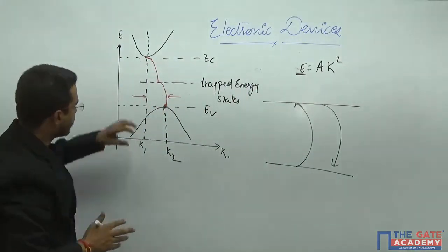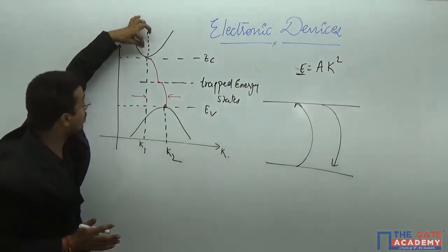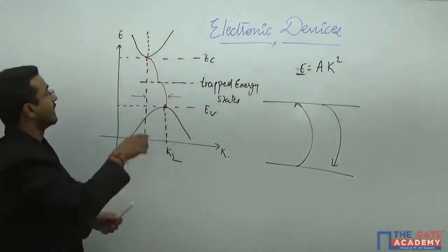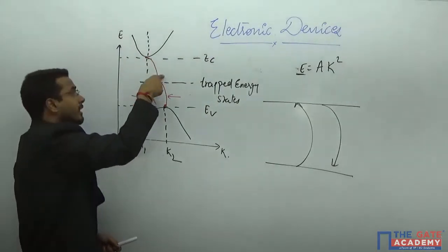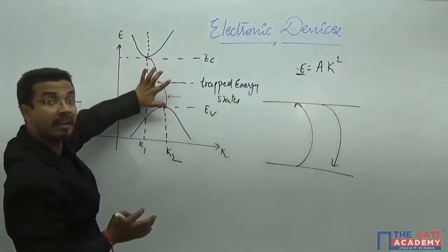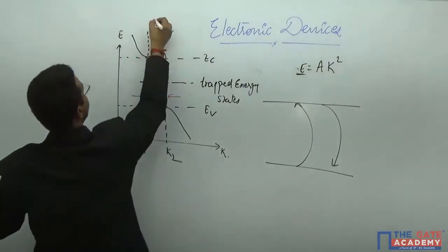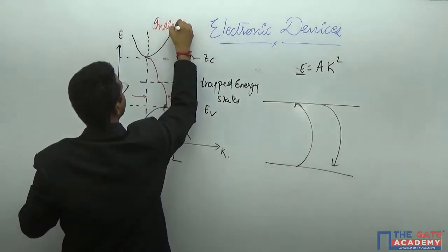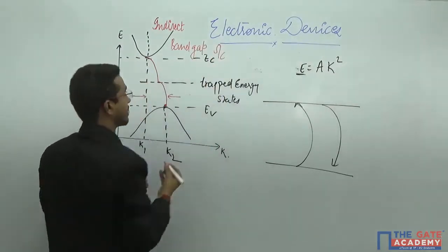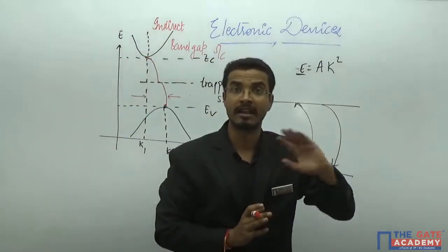Yes or no? In this type of semiconductor, the transition of the electron from the conduction band is not happening directly to the hole location. Now see, it is coming from here to an internal energy state, and then from the internal energy state to this state. Whenever this type of transition occurs in the recombination process, this type of semiconductor is known as an indirect band gap semiconductor.